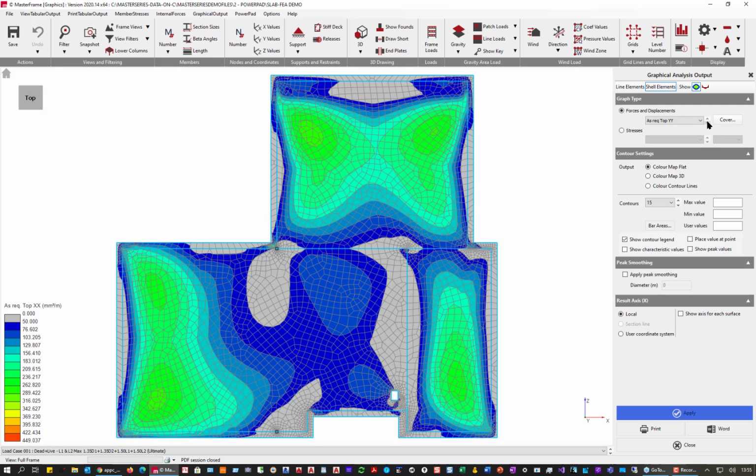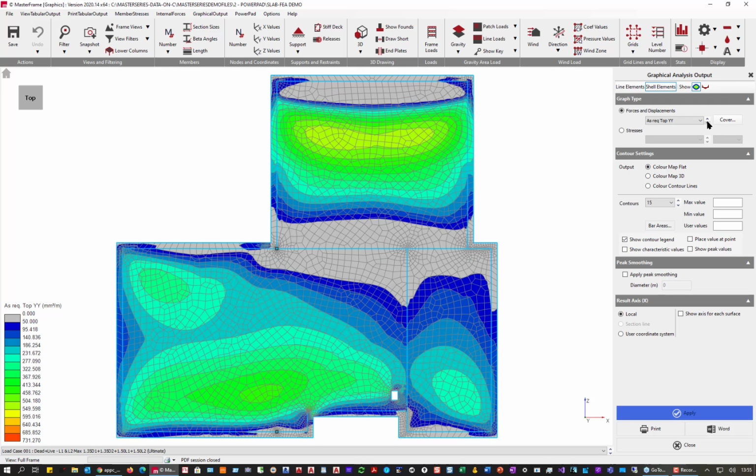Happy. On the top we can get away with possibly a bit more than the 393 is required in these areas. Yeah, it is. So you're going to need a bit more in the YY. So those are all very, very useful for you in designing your slabs.